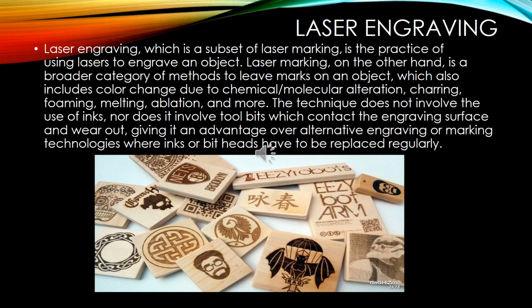replaced regularly. Some of the materials that you can engrave with these techniques are natural materials. The marking of organic material like wood is based on material carbonization, which produces darkening of the surface and marks with high contrast.